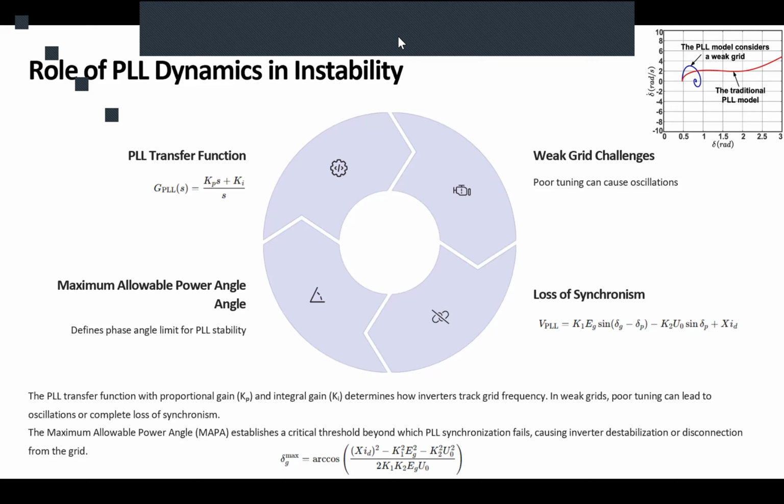If we pass that delta, meaning the error is large enough or oscillating or behaving critically or chaotically, then the PLL would not be able to follow the errors and therefore would not be able to synchronize to our system. Are we good so far? Any questions?